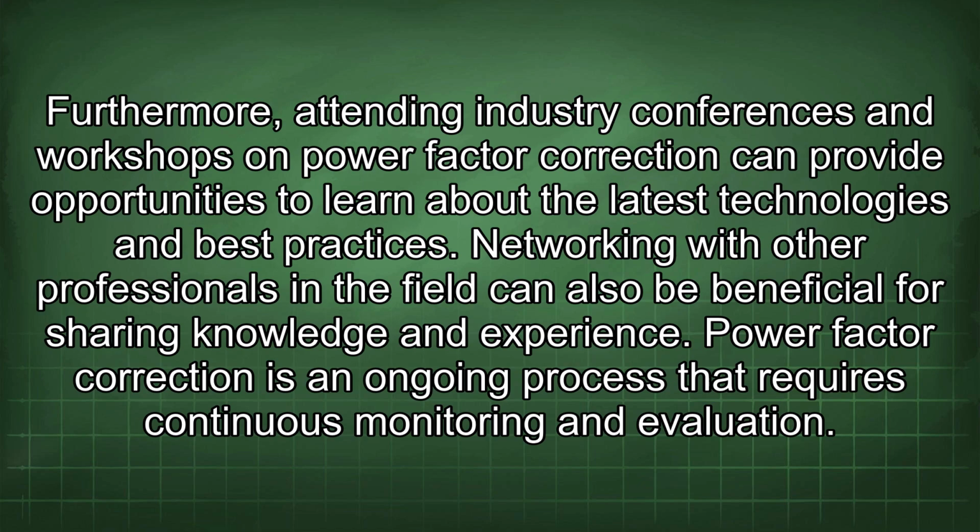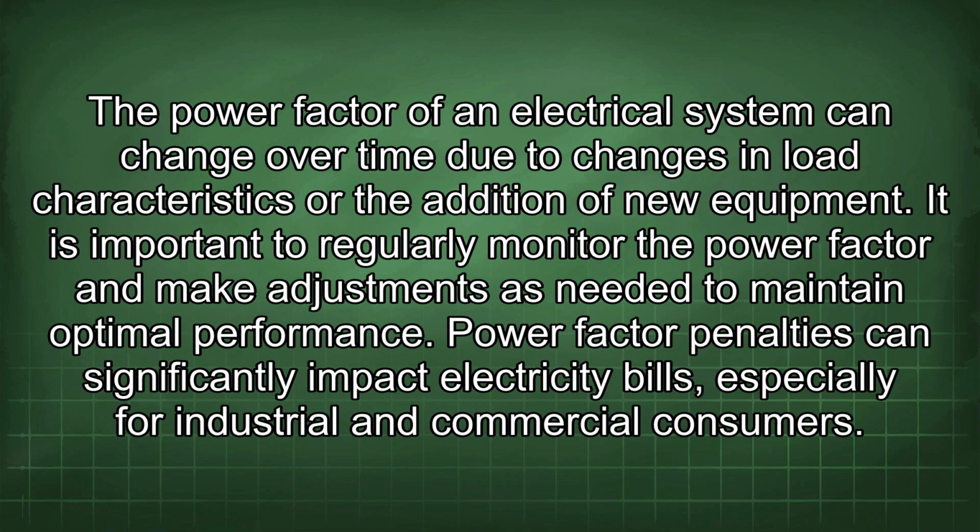Power factor correction is an ongoing process that requires continuous monitoring and evaluation. The power factor of an electrical system can change over time due to changes in load characteristics or the addition of new equipment. It is important to regularly monitor the power factor and make adjustments as needed to maintain optimal performance. Power factor penalties can significantly impact electricity bills, especially for industrial and commercial consumers.